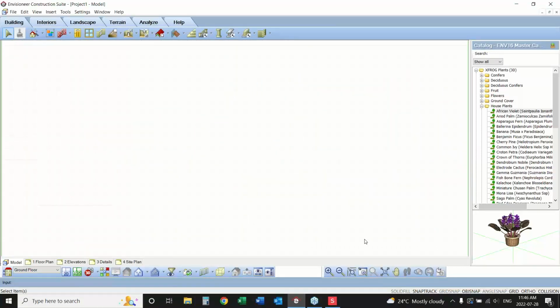And with this new blank drawing, it brings in all the settings that were saved with that drawing. What we're going to do is change those settings to be our preferred settings and then resave it as a template. So one thing that I don't ever use is the grid. So down in the lower right, I'm going to turn off the grid. So when I start off a brand new drawing, it's not going to have the grid on for me.